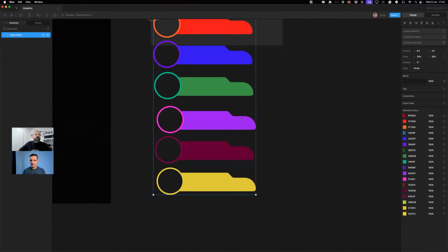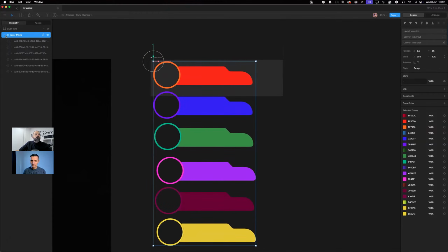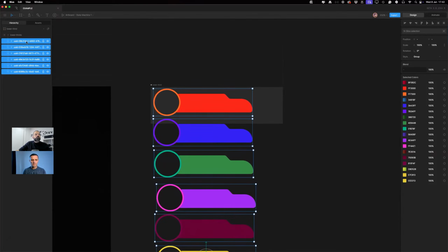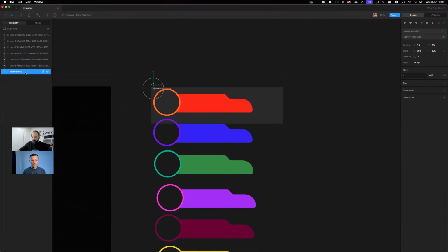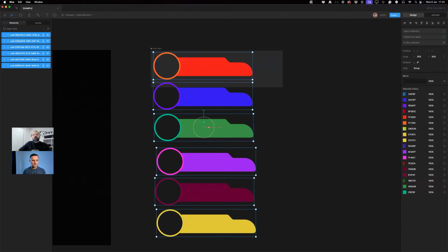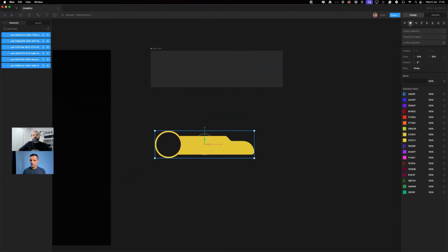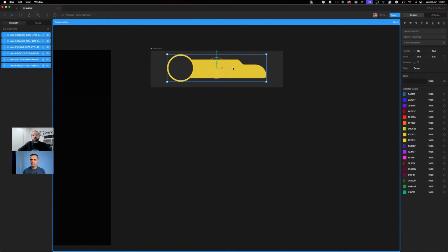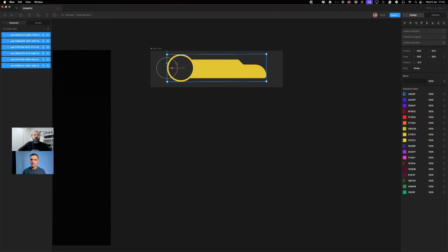Now that I have my lower thirds, I have the hierarchy here. I have the different elements and I want to ungroup them. So I will ungroup these elements and align the lower thirds immediately here. You have the anchor point, which is here. For example, using the right shortcut, which is Y, you can put the anchor point here for a rotation from here. It's not working because I didn't define it, so I will define it. And then you can put the anchor point where you want.